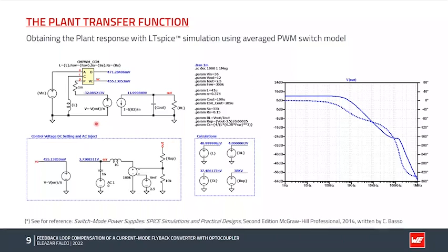You might have to do some small adjustments to the SPICE netlists provided, like for example, also modeling the transformer with two arbitrary sources depending on each other, like here, because the model needs to operate in DC, to set the DC operating point, but also in AC. But anyway, these are small modifications which are not difficult to do.